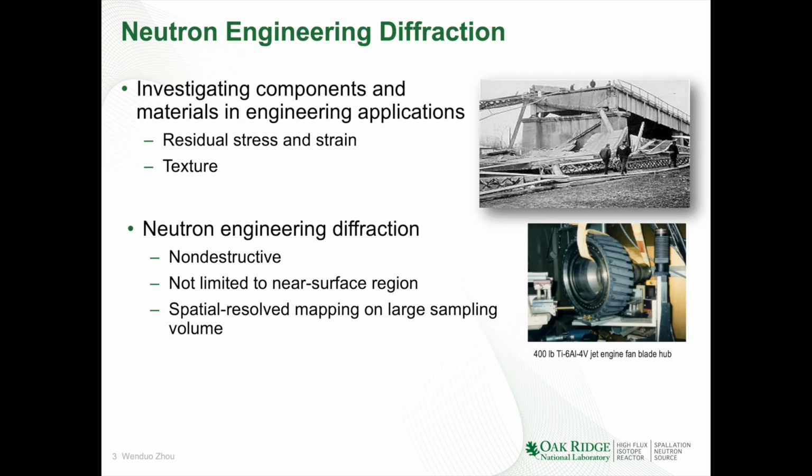Beamline HB2B, with acronym HiDRA, is built to study residual stress, strain, and texture of materials like iron, steel, and various types of superalloys. These manufactured materials are widely used in construction industry. Residual stress of this type of material is of great interest to study. It can be detrimental, causing premature failure or early crack propagation. On the other side, if properly engineered, it could extend useful life, prevent premature failure, or increase safe elastic limit.